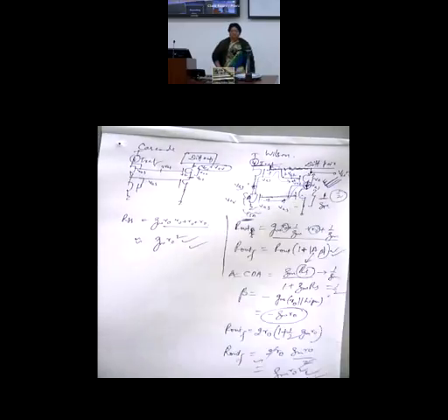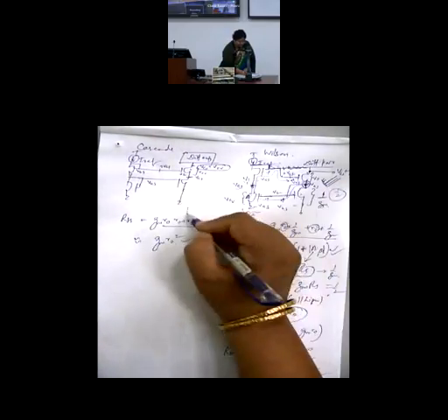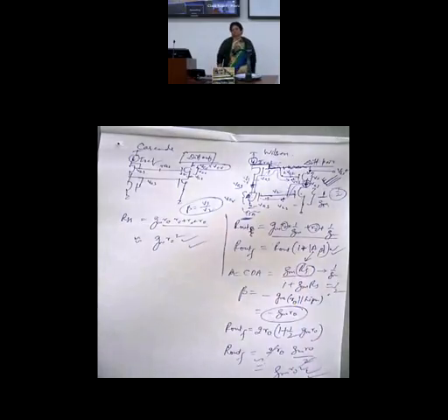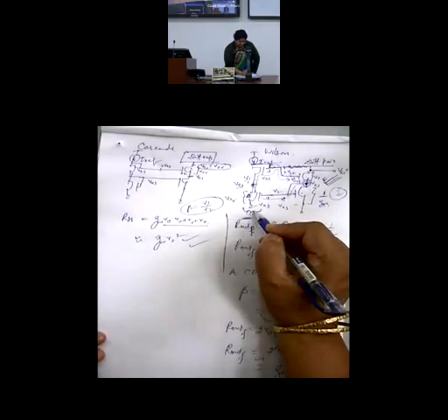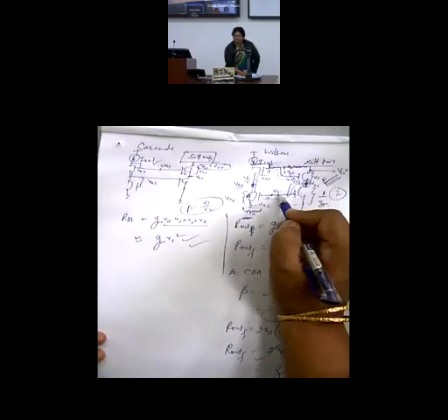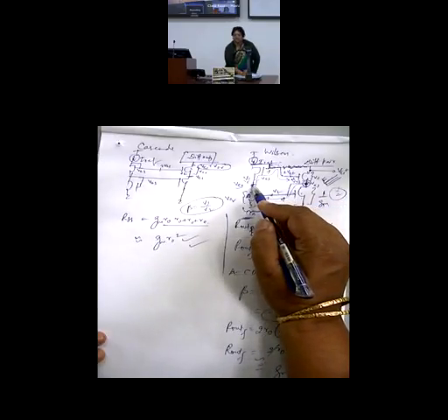So look, you have to find the gain. If I say this is V1 and this is V2, beta is nothing but V1 by V2. What is V1? If I say that this is behaving like a common source amplifier, because any perturbation here comes here, goes as input to this transistor, produces the output here. It is a common source amplifier configuration.